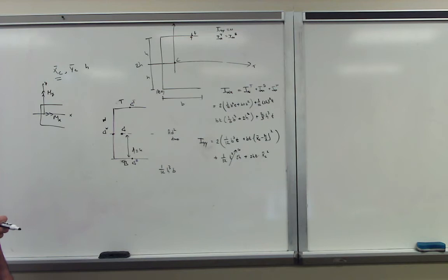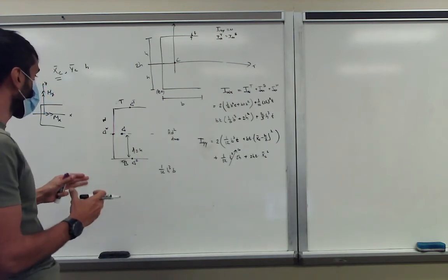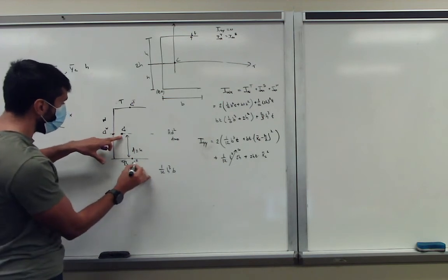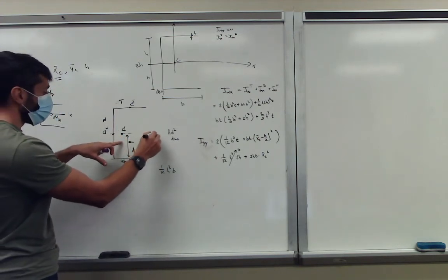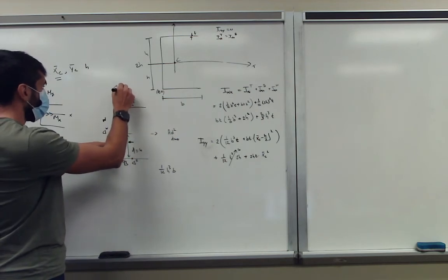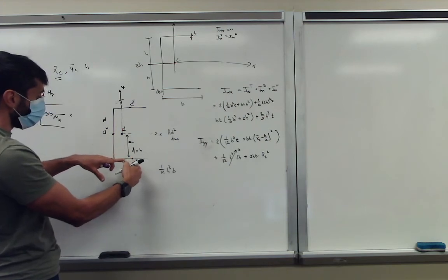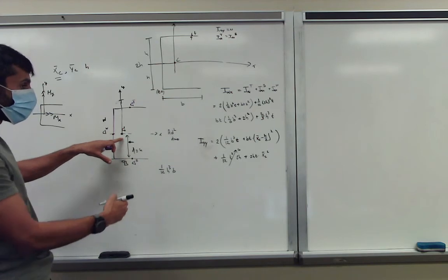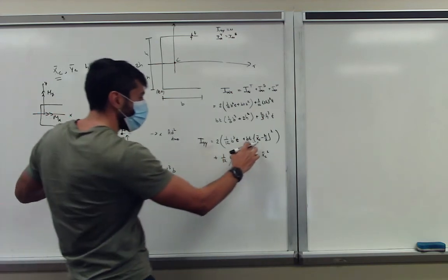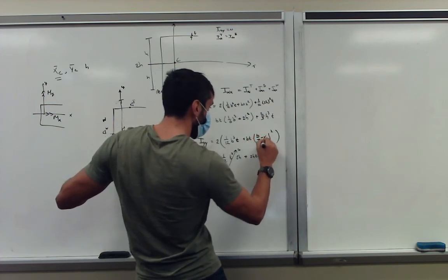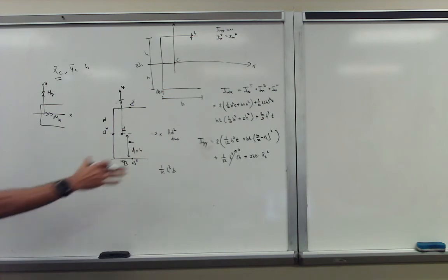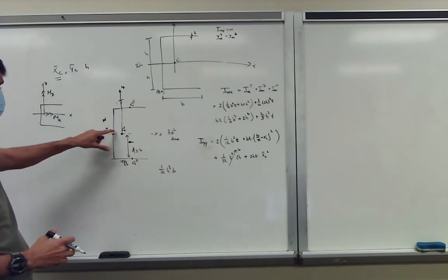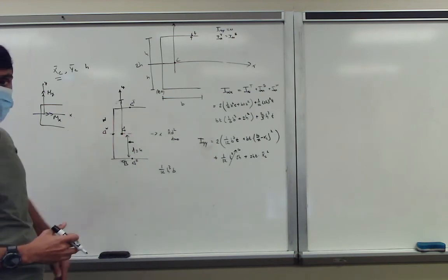Could you clarify the Steiner factor on IYY real quick, like the XC minus B over 2? Yeah, so you always have to ask, how does the shift occur? This is your centroid here, and I go from the centroid of your local axis system to the centroid of the cross section. So in this case, you go to the left, if this is positive defined, so you're going from CB to the left. So you take CB minus, this is actually, it should be B over 2 minus CX. Okay, yeah, that makes sense. Yes. Because you go to the left, you go from plus to negative. The other side will be positive. Right, yeah, that makes sense. Yeah, good spotted. And in this case, it will be equal to basically negative CX, because you go from here to there.